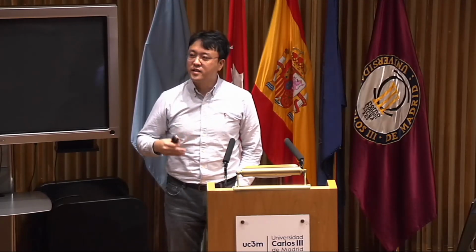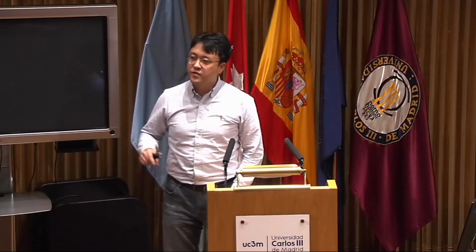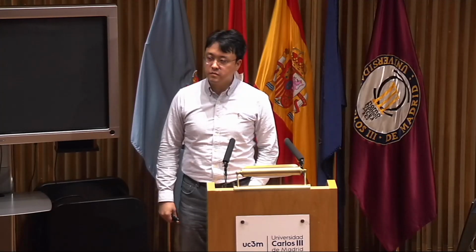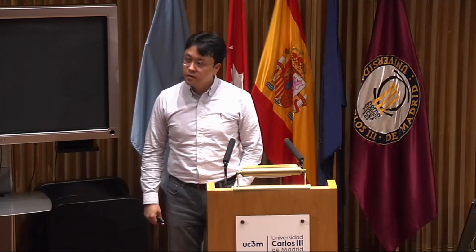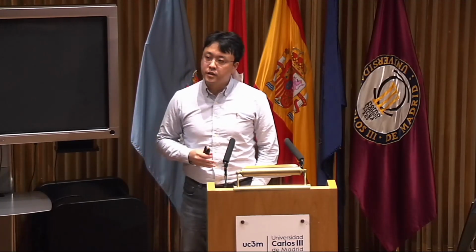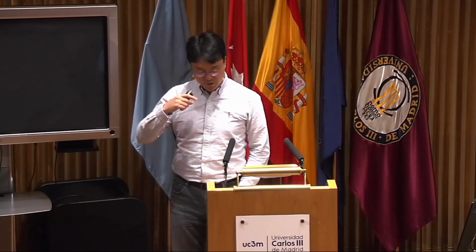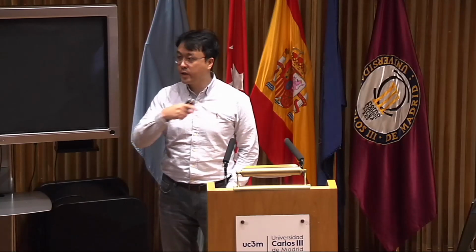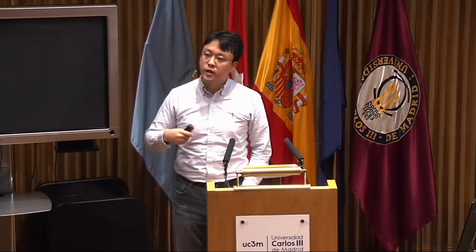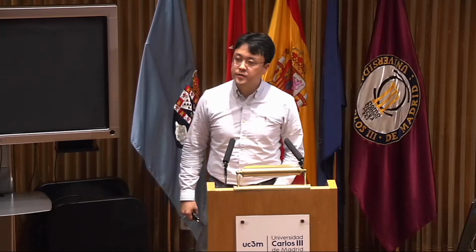And why is 2 megahertz better? Because 2 megahertz is a commercialized frequency for the semiconductor industry. So you will probably have to change the coil, the antenna, and redesign it to have the same matching. Yeah, exactly. We need to slightly modify the design factor of the RF antenna depending on the frequency. So when we choose 2 megahertz, we need to modify the antenna structure. Thank you very much.